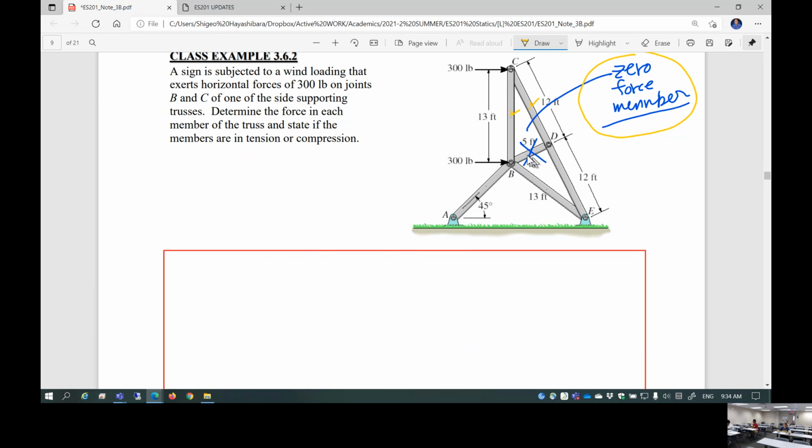After that, knowing this internal force, I'm going to pick up the joint B. Joint B, ignoring this, you have two unknowns. This is known already, so you can find out this and that. And after that, what? I'm going to pick up this. Pick up this means that this internal force is equal to this internal force anyways. That's it. Everything's done. I don't need to know reactions. Does it make sense? So this is the strategy I'm going to choose.